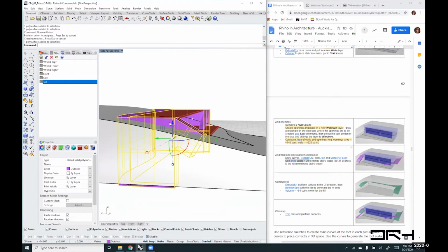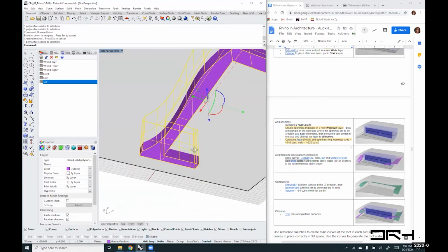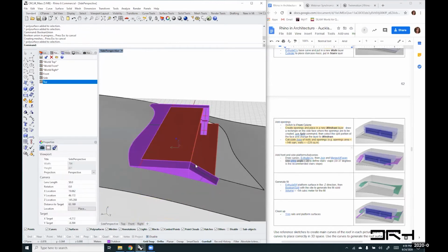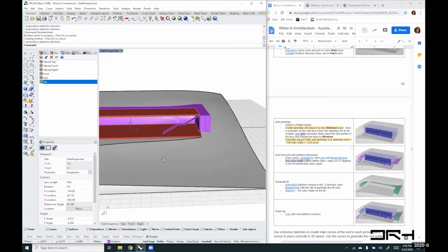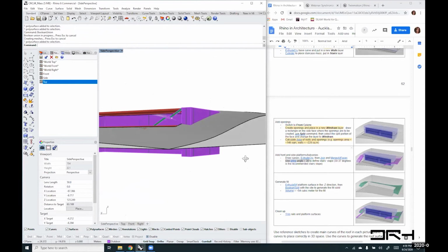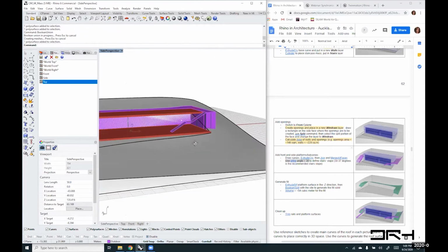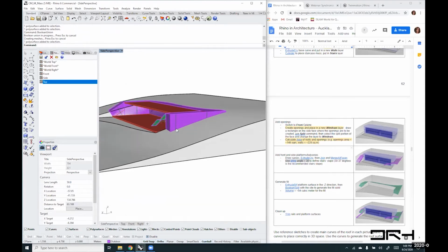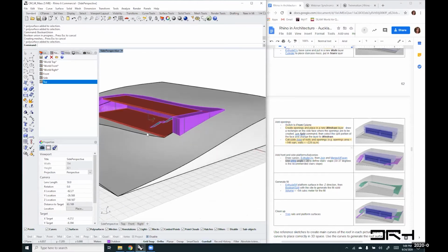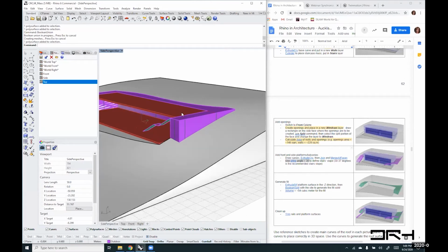And now I have that really gigantic fill that intersects with the site all the way through, that I don't really need. I didn't need it to be that big, but you can make it as big as you want so that you are sure to have it intersect all the way through. And it doesn't matter really, even if it's big, because what we will do is a Boolean split.